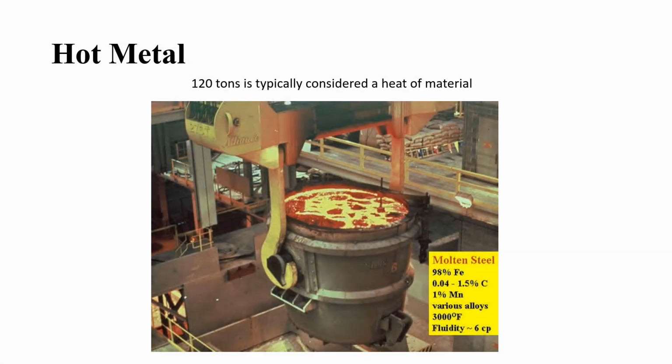When discussing metallic materials, you will often hear the term heat, or heat of material, or melt. In the pre-production of steel, iron ore is melted in a blast furnace and mixed with coke, the carbon residue of coal. The molten iron is then poured into ingots referred to as pig iron. These are simply lumps of iron that vary in size and form. They are used as feedstock when making steel. It is the principal raw material in making steel and is stockpiled for use as needed.